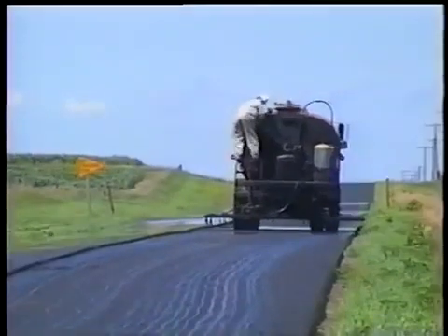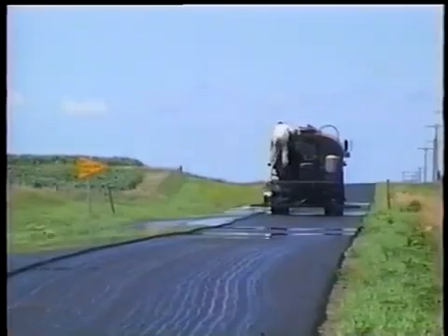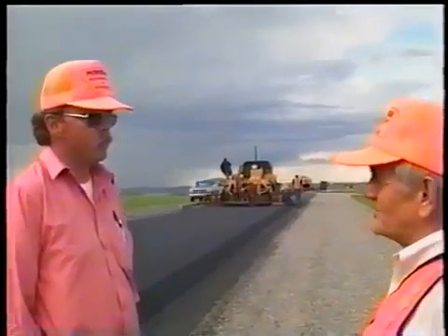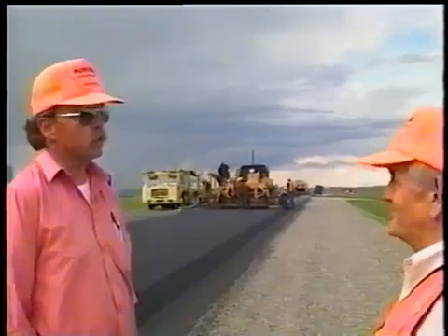Winds by themselves may not be cause to avoid paving, but they sure can mess up the tack application and cool down the mix real fast. So use good judgment. If weather conditions prevent good work, take the necessary action.